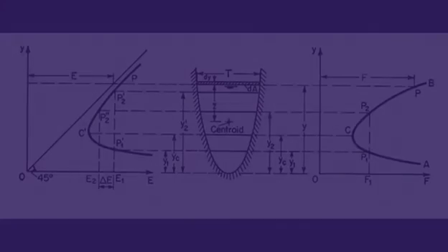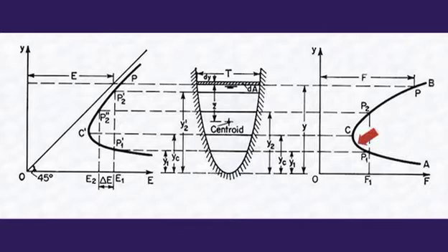The units of specific force are force per weight per unit of volume, that is, volume units. The specific force curve is a type of hyperbola similar to the specific energy curve, with a minimum value of specific force corresponding to critical depth. The minimum specific force is obtained by taking the derivative of specific force and equating to 0.